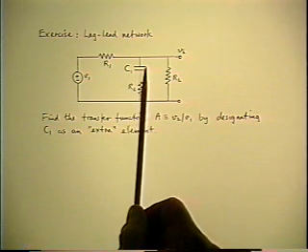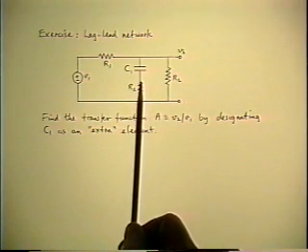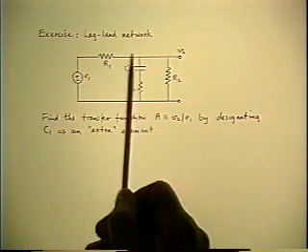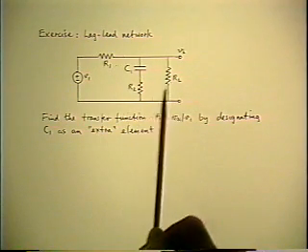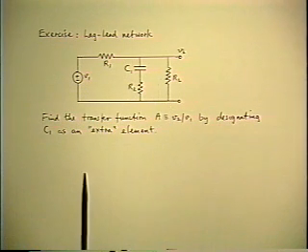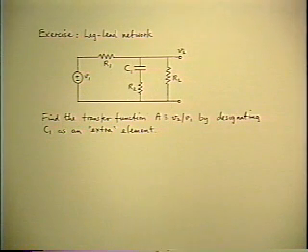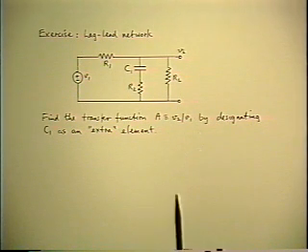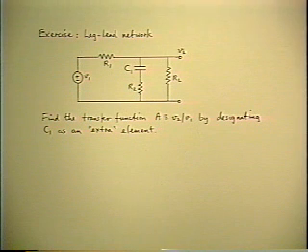On the other hand, if you replace the capacitor with a short, which you could equally well do, then what you're saying is the reference circuit is now the high frequency flat gain. And so the high frequency gain will come out in front as the reference, and the pole and the zero will come out inverted. So you have the choice which way to do it, and the choice is determined by which way you want the answer to come out.